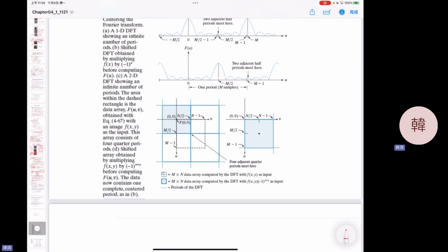So can you tell me what's the inverse transform, the IDFT, of this signal? If you have a strong frequency signal processing background, you know the rectangular function's inverse transform becomes a sinc function. Sinc is sine x divided by x. We call it sinc of t, which is sine t divided by t.